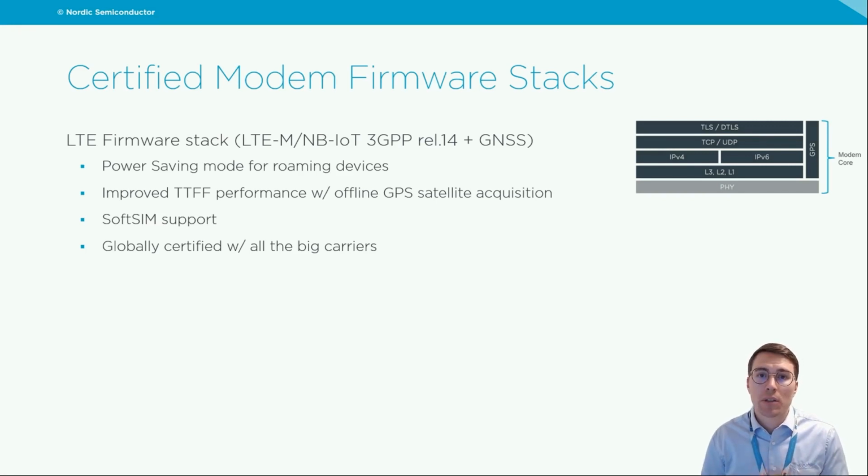This has been an issue for a long time, using a SIM card that's roaming on a network and not getting the actual PSM timers from the network. So now we have added a new feature on our device side that gives you this. Also improved time to first fix performance with something called offline GPS satellite acquisition, and soft SIM support, of course. And we have this stack globally certified with all the big carriers. That's the plan for this stack.